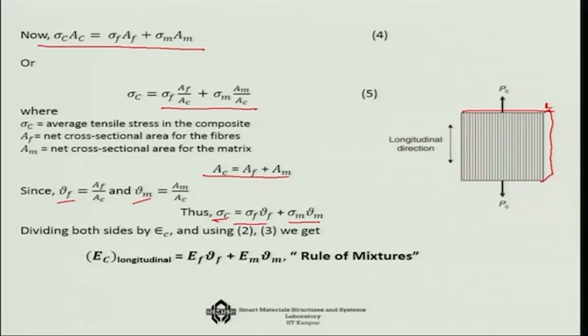Interestingly, this is also following the rule of mixture, but for a different reason, because of the load share. Similarly, if you put this epsilon C in terms of the strain, you will see the EC longitudinal also follows the rule of mixture as EF VF plus EM VM. So that is in the longitudinal direction.